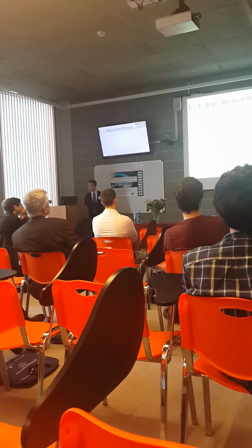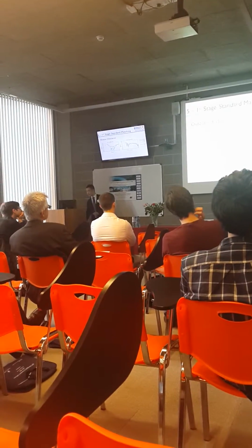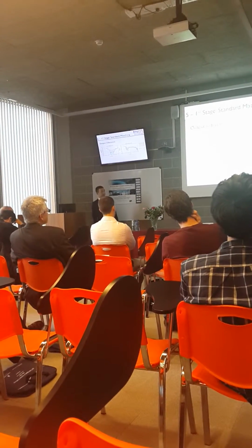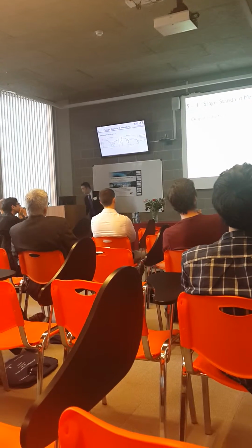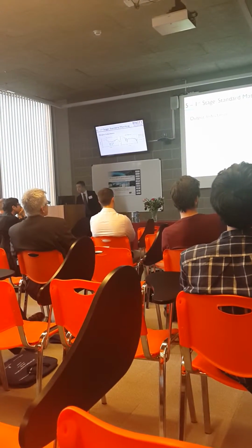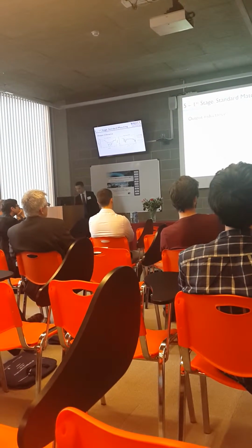And just to improve a little bit for the S22, the output inductance value changing from 1.5 nanohenry to 2.7 nanohenry is examined. I'm not going to show too much detail for this one, but at 1.8 milliamp, the blue line shows a better result here.